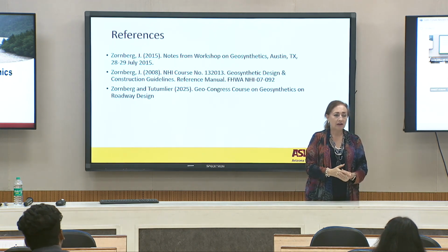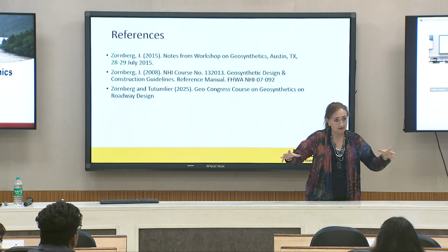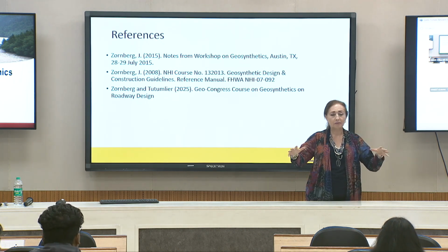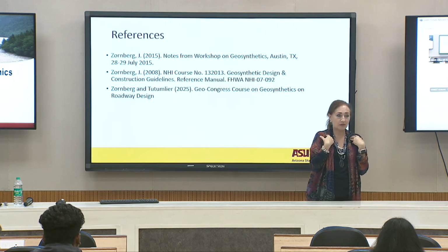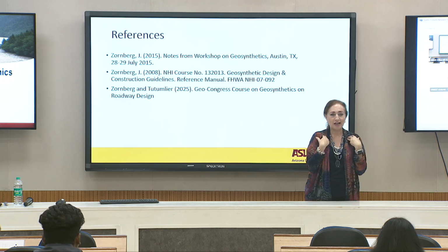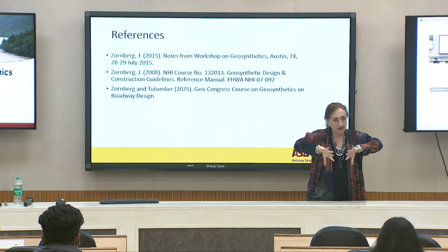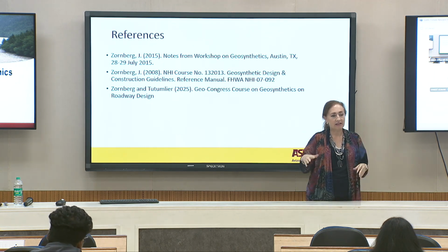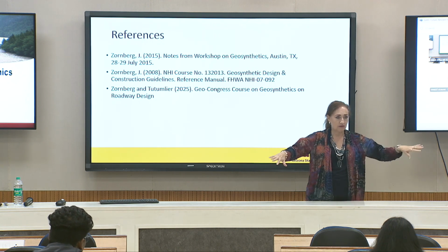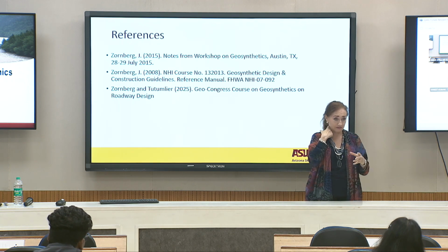But if you're talking about the stabilization of the ballast by itself, the problem with the ballast, from what I understand, and I'm not an expert on that, there is a big group in Australia working on it. It's great. Basically, what happens is the ballast tries to spread out, and loses strength because of that lateral spreading. In that case, geogrids.